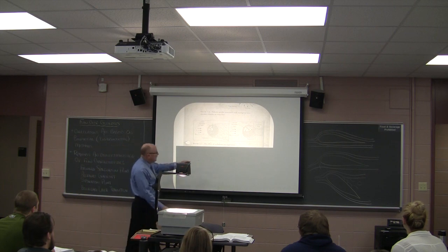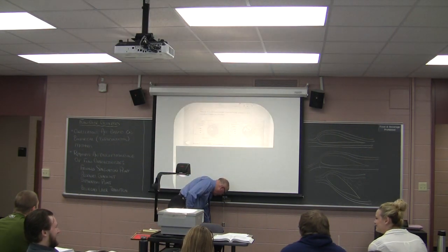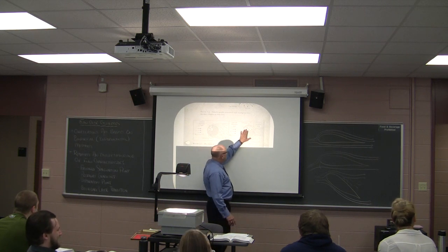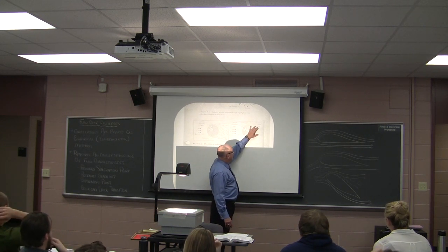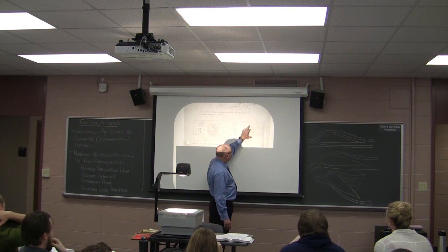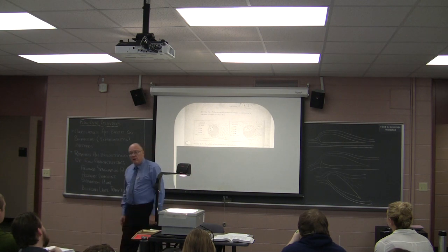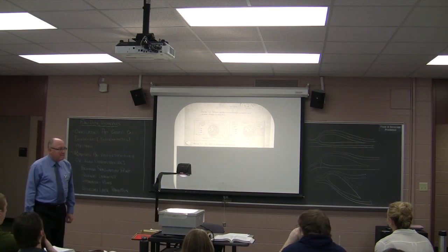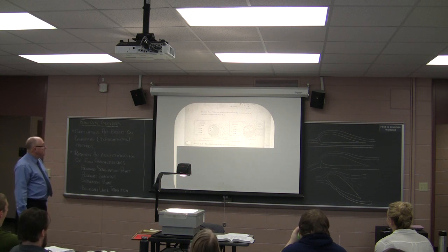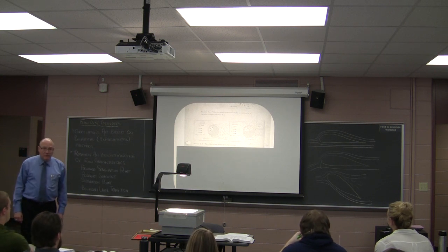As you can see in this one, the separation angle is extended considerably, and you have quite a bit more adherence of the boundary layer because the flow is turbulent than you did in the previous example where it's just laminar flow. Okay. Any questions on this?